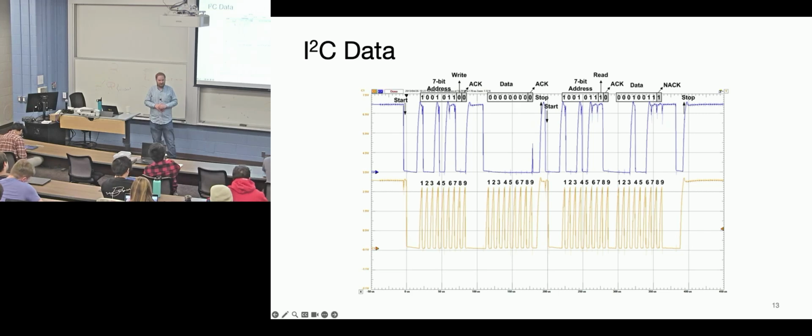So it would just write again to somewhere different? Well, then what do you do if you get a NACK? That's up to you as a programmer to make that decision. You might say, I've written this protocol that if the device doesn't respond, then I go talk to these other ones, or I throw an error to the user. Who knows what happens? But you'd have to make a decision what to do.